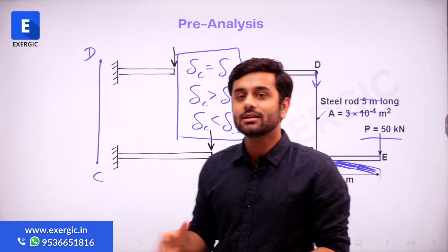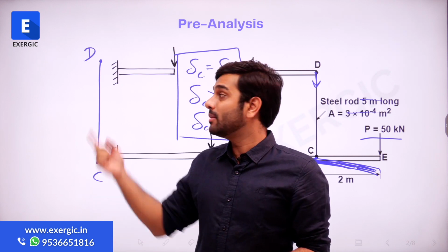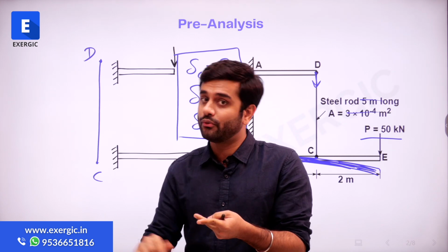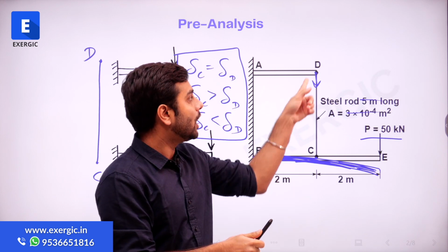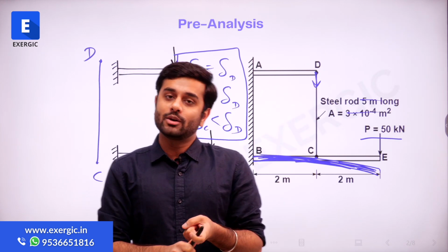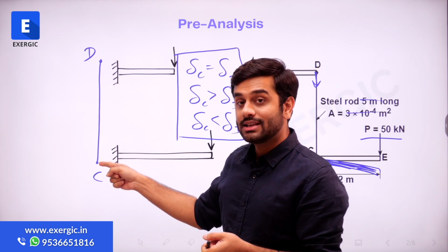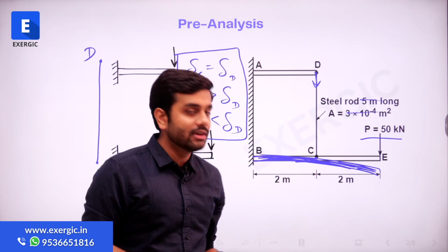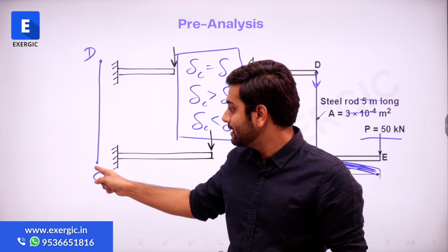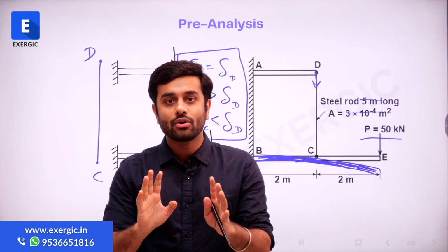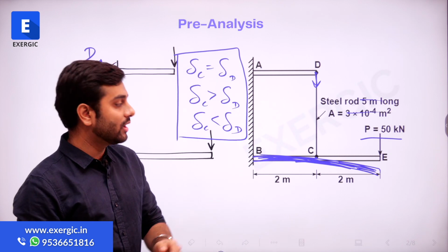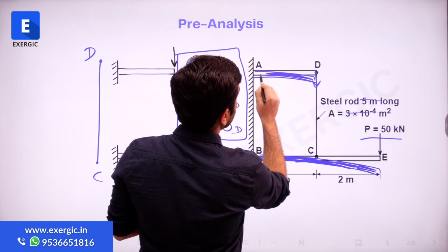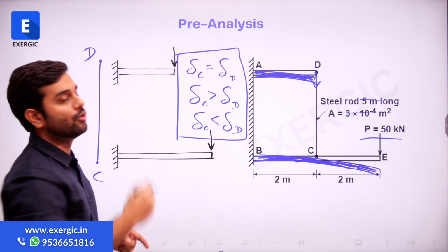If the distance does not change, then it is no load at all. Or maybe the material is totally rigid, which is not the case here, right? Neither of the cases are present. Force is acting, definitely. If force is not acting, how will D get deflected? Force has to act. It means the distance between C and D will change because it is not rigid. And since that force is going to be a tensile force, we can say for sure that the distance between C and D will increase, right or not? And that can help you to relate the deflection of C with the deflection of D. How? Can you answer it now?